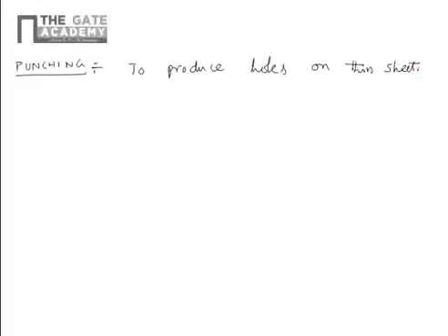There also, if you observe, you will see the punch, a small circular shape punch, as well as the die, which is supporting downside, that is called die. So to produce holes on the thin sheet in punching, size of the punch equals size of the hole. Objective is you want to produce a hole of diameter 10 mm, then size of the punch you have to take is 10 mm.